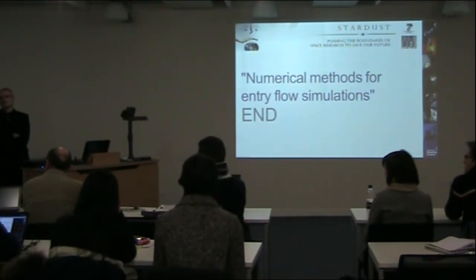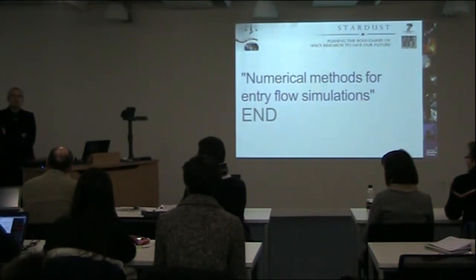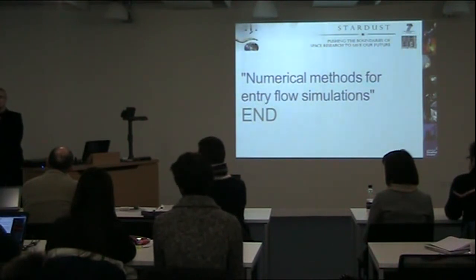It's a very lengthy process, and we can now do it optimizing the control of the surfaces of the vehicle to pinpoint a location on the ground. So we solve an optimal control problem coupled with a numerical simulation. How big a supercomputer do you have? Well, we use multi-fidelity techniques, so the vast majority of the computation is done with low-fidelity models, and then high-fidelity models are used just to correct the predictions.